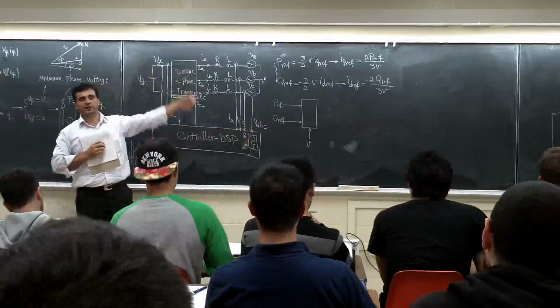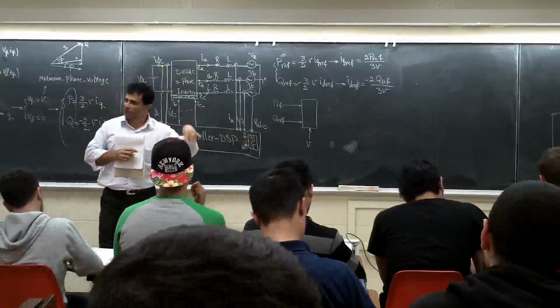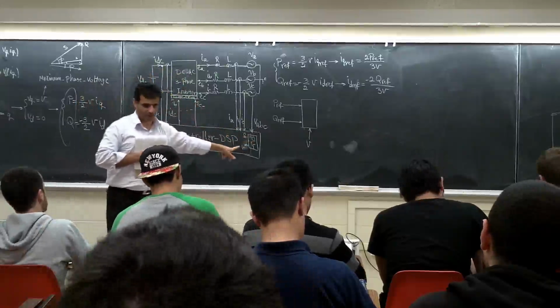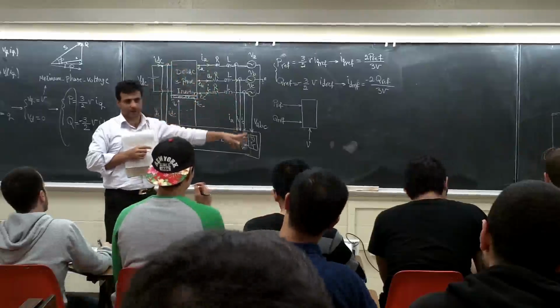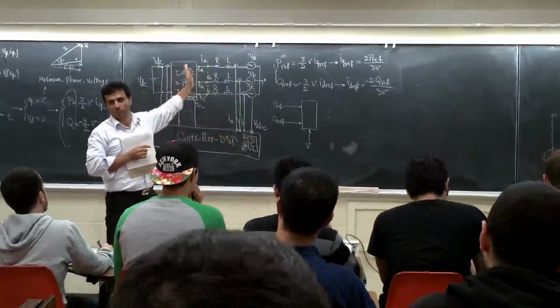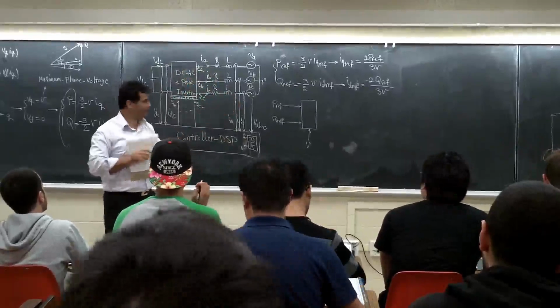It's going to measure the voltage and phase online. Even if the grid voltage changes a little bit, this guy is going to tell us how much. But as I said, forget how it's going to calculate. If we assume the grid is fixed, you can calculate V based on what I put here: 480 divided by the square root of 3 times the square root of 2, right? That's what we have.